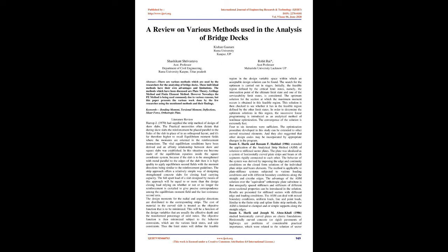Isam E. Herrick and Bassam F. Haddad, 1986, extended the application of the analytical strip method, ASM, of solution to stiffened sector plates. The plate was idealized as a system of horizontally curved plate strips and beam or rib segments rigidly connected to each other. The behavior of the system was derived by imposing the edge and continuity conditions on the closed-form solutions of the individual plate strips and beam elements.